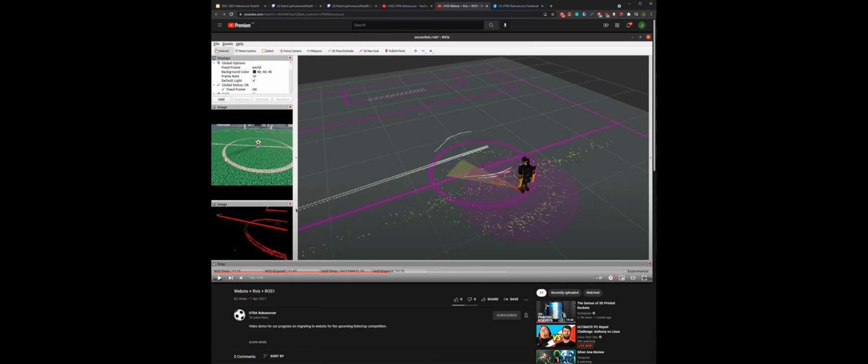This is the original image from the webcam, and then this is what we get through OpenCV augmentation. Essentially, we extract all the white lines and make those into points. We take these points, this is what's printing out here. We're not oriented properly, so it's not lined up. And then we use these points as reference for our localization algorithm, which generates these green dots, where each one represents a probability of where our robot can possibly be.